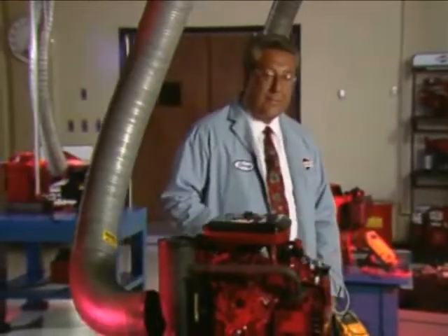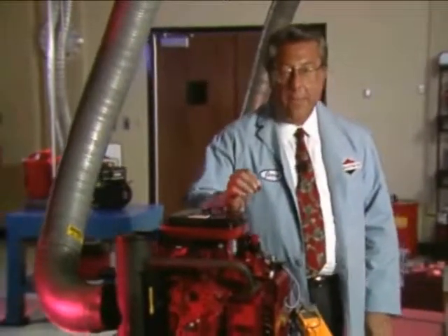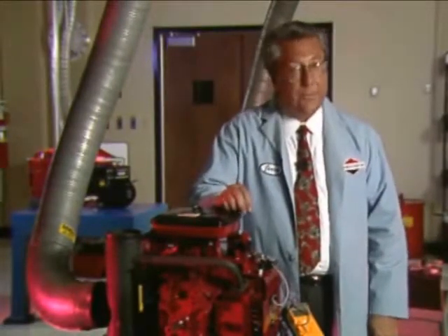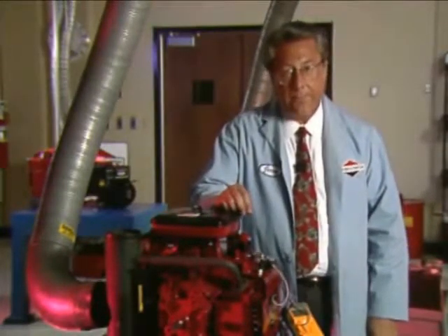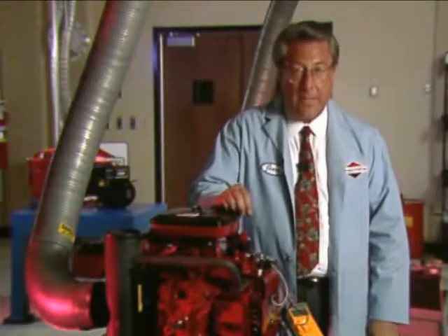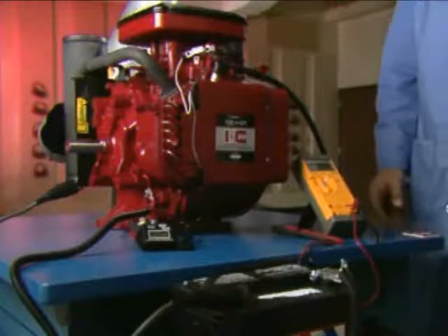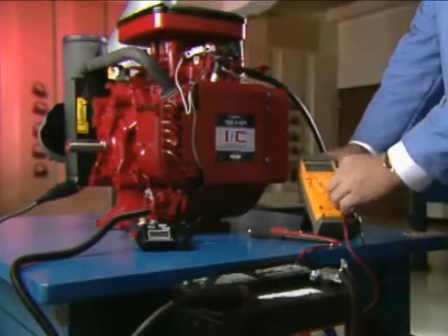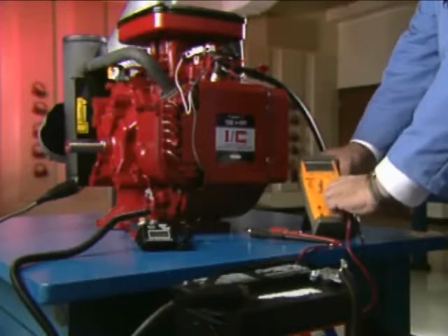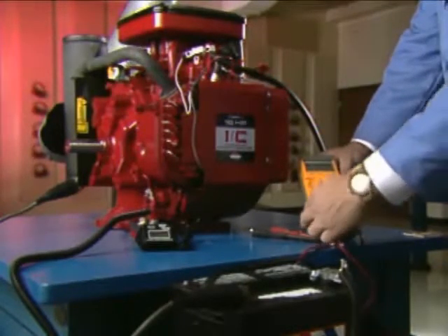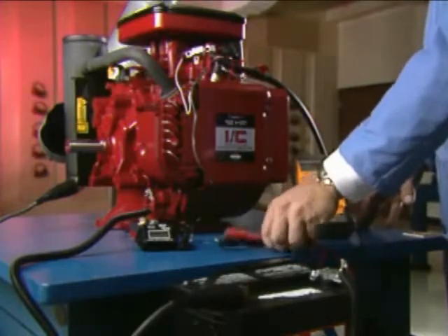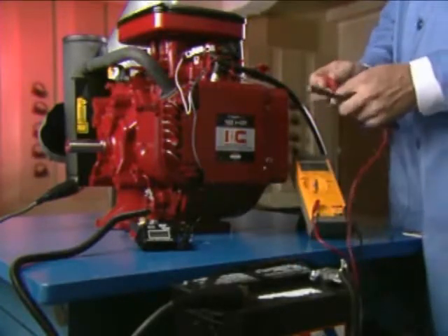The next test is a DC amperage test. This test is used on alternators that contain a rectifier, either in the stator or in the stator harness. It can also be used to measure the output of the rectified and regulated system. The first step in this test is to properly set and connect your multimeter. When measuring DC amps, it is necessary to connect the battery in series with the meter. Failure to do this can cause damage to both the stator and the meter.